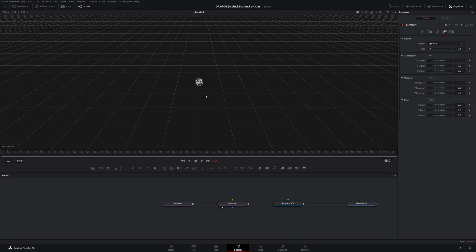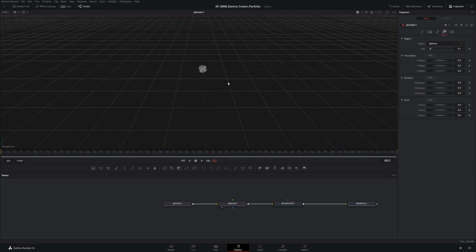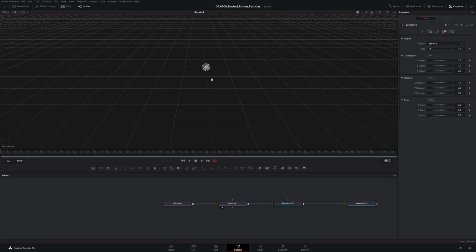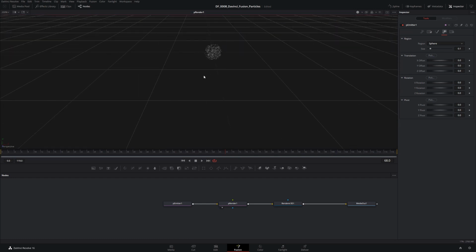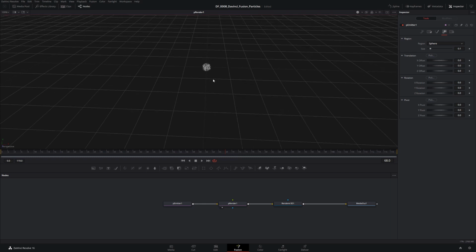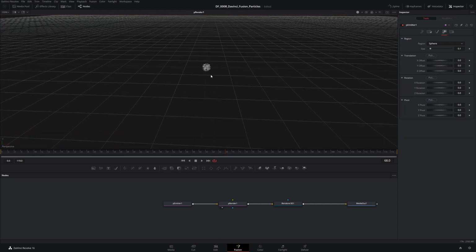So in terms of navigating around this viewer, I can hold the middle mouse button down and move back and forth. I can use my mouse wheel and scroll up and down this way. I can hold control with my mouse wheel and that'll zoom in and out. And I can hold alt down, and then when I'm holding my middle mouse button, I can move my mouse around and rotate around things here.